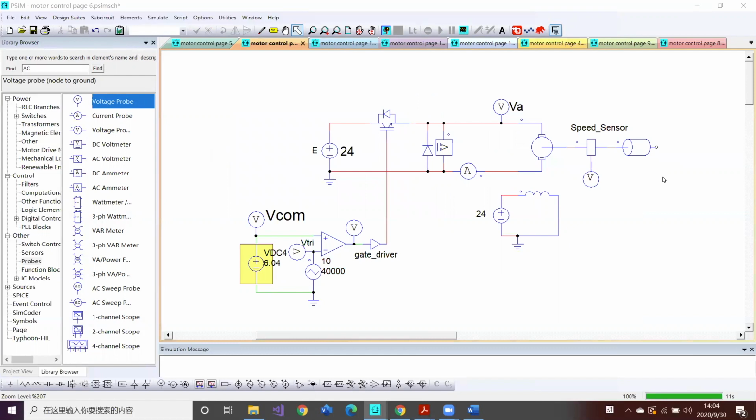You will find something that looks like this. This part is what we call a chopper, also named a buck converter. The input voltage we have is 24 volts, but as we found, we need 14.5 volts to make our motor speed 1,500, right?